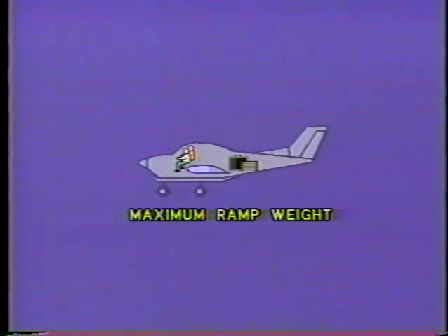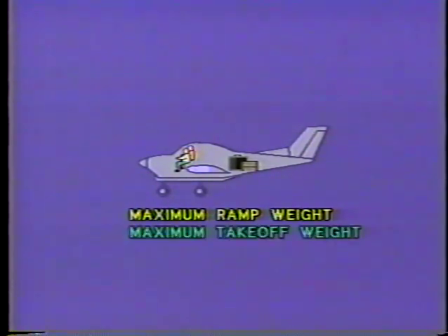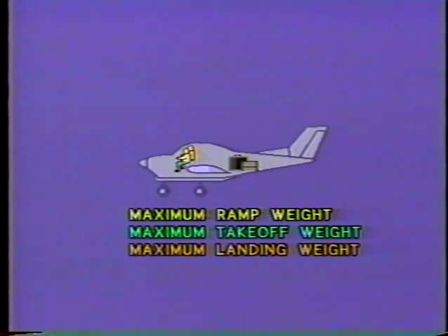Maximum ramp weight is the maximum weight approved by the manufacturer for ground maneuvering. Maximum takeoff weight is the maximum weight approved for the start of the takeoff run. Maximum landing weight is the maximum weight approved for the landing touchdown.